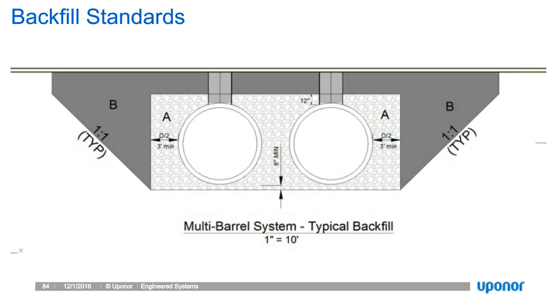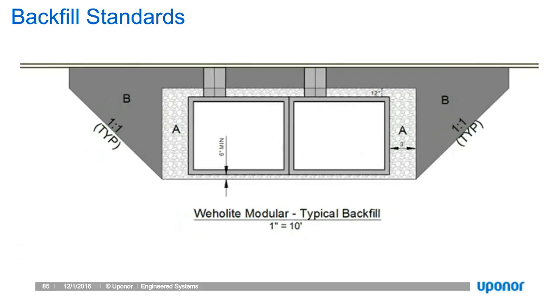So ASTM D2321 defines, again, as I was talking about earlier in the CANDE analysis, a critical backfill zone A, non-critical select backfill zone B, subgrade, and then the surface above the structure. That same consideration in a rectangular form would be the same.